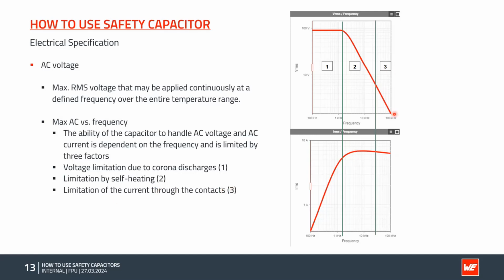It really depends on how the pins are connected to the product, and also to the PCB, what kind of currents and voltages with regard to the frequency you can apply. These graphs are not available in a data sheet. Mostly it's available through different tools. For us, it's accessible through our REDEXPERT online tool.